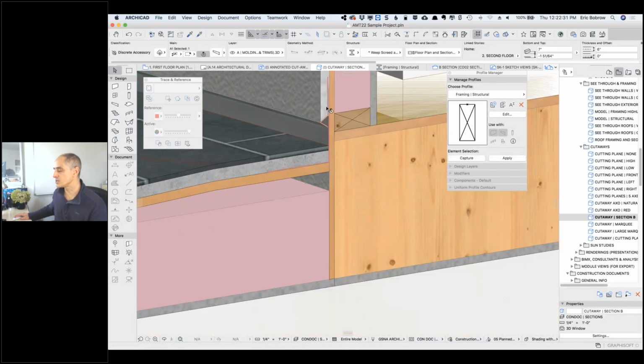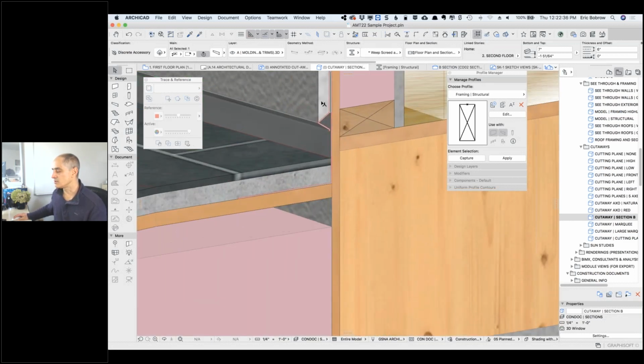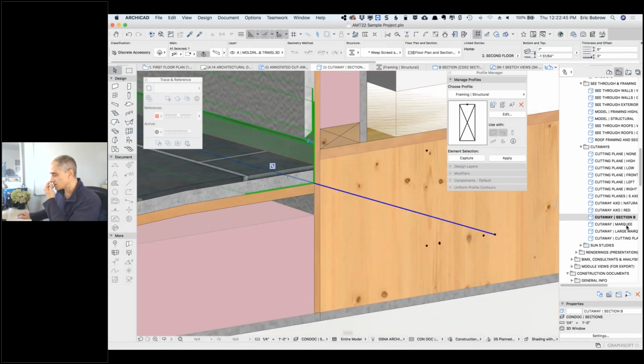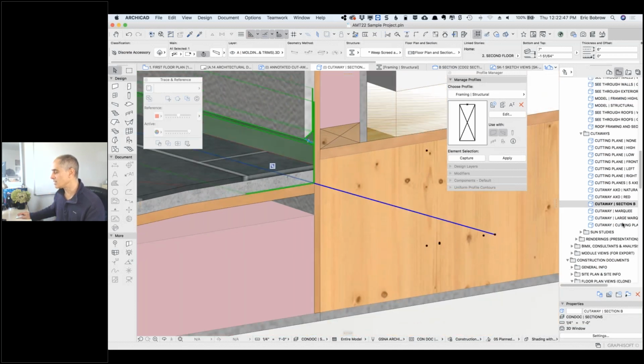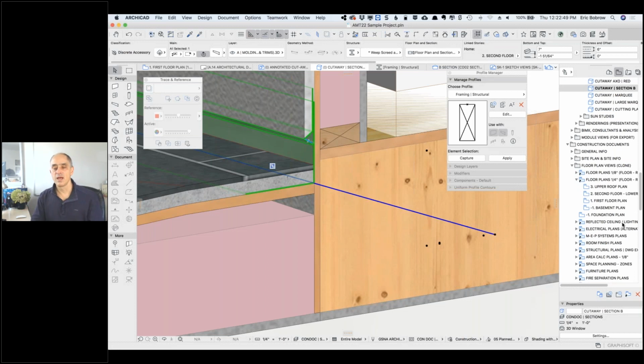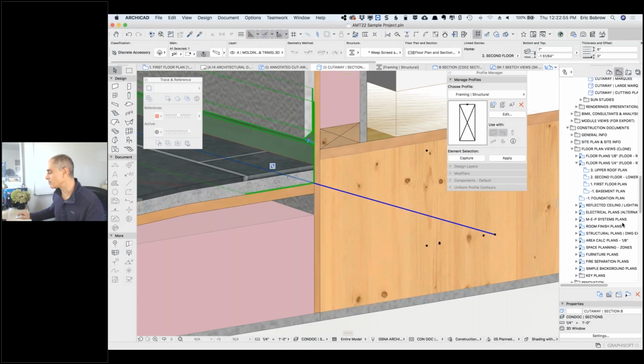You can see what this is. This is a complex profile called a weep screed here, and the stucco is dying into this, and then of course it's going underneath this here. Now let's take a look at this detailed drawing, and again, you can do this yourself, but having this as a way to study how it was done is very powerful.